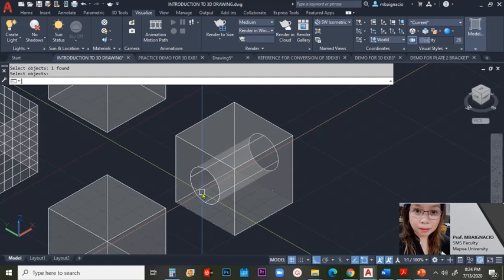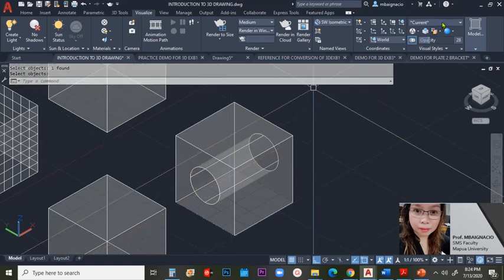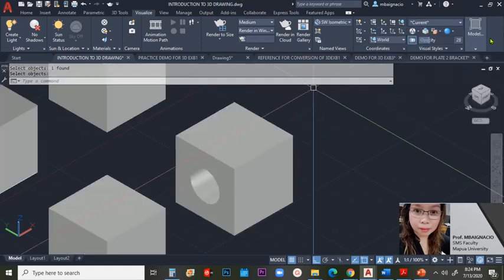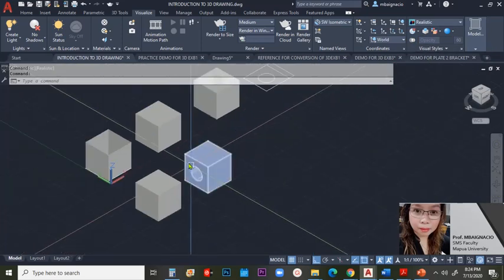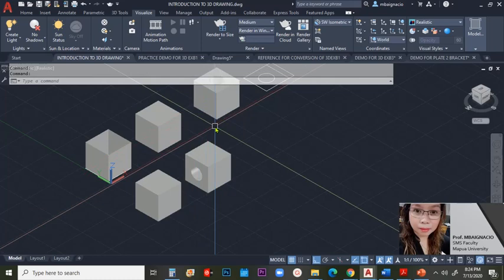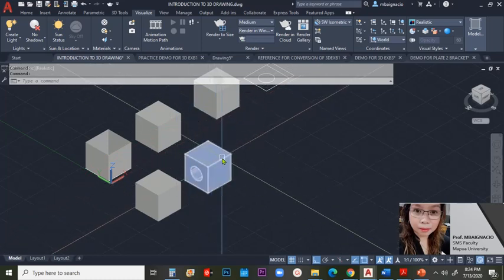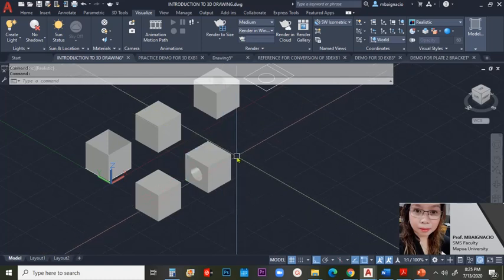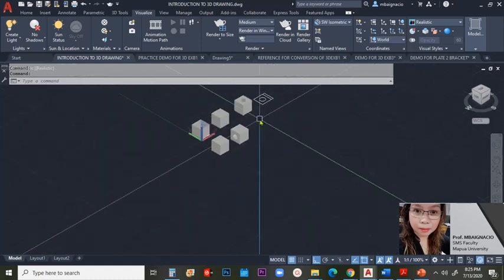Automatically, as you can see, it is open from the side, front face, and side at the back. To confirm again, you go to realistic, and you have this opening. So you can perform this, try it out. Perform extrude and then subtract using these boxes with an area of 10 by 10 by 10, and then we shall continue working with the last figure.